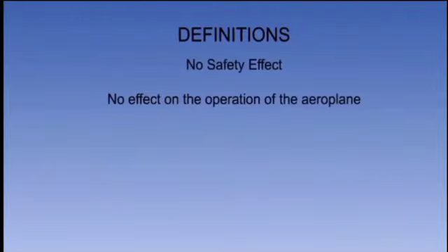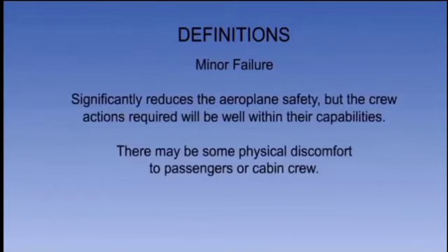The lowest is the no safety effect. This is self-explanatory. It will happen with no effect on the operation of the aircraft. And next is the minor failure. This failure condition will slightly reduce the airplane's safety, but the crew actions required will be well within their capabilities.